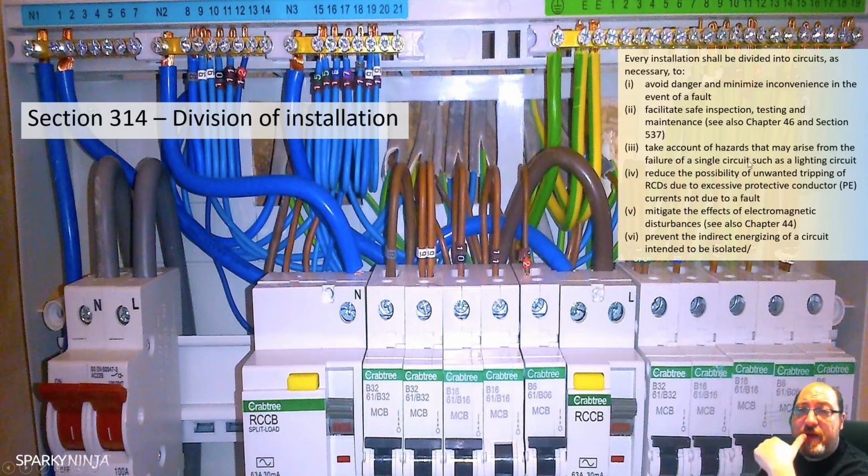Take account of hazards that might arise from the failure of a single circuit. In typical domestics, we'll have on this RCD upstairs lights and downstairs power, and then up here upstairs power and downstairs lights. So that should one go off, you have the other. You know, you get that. I may have said that wrong, but you get the arrangement. The idea is to always have a power supply on a level so you may be able to facilitate lighting. And unwanted tripping, we're going to cover that later on.